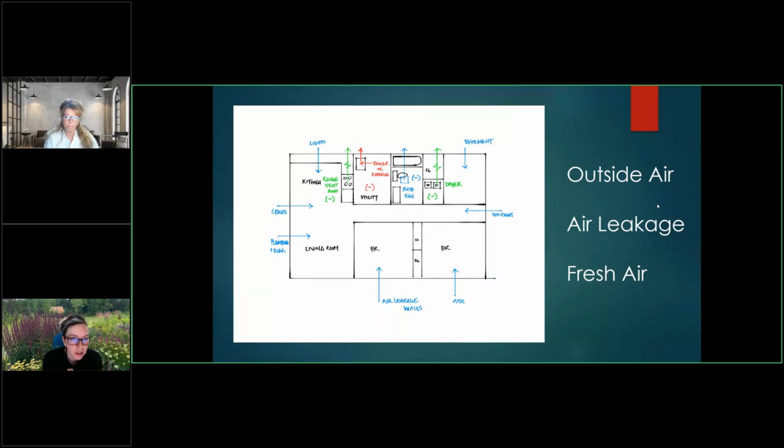Air leakage is through the structure. And as architects, hopefully we've learned a little bit about typically the places where the air leaks are usually the least likely. The air leaks aren't always coming through your windows. They're coming from the basement. They're coming from the band joist or box sill. That's one of the leakiest places in our structure. So they're coming from below the structure. They're coming through every chimney that we put into the attic, especially in those hot, humid climates, attaching to whatever the insulation is and coming inside.